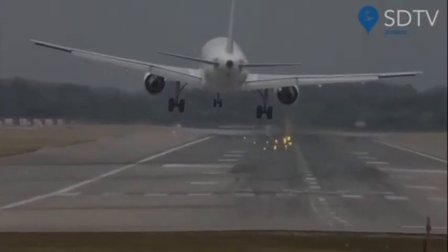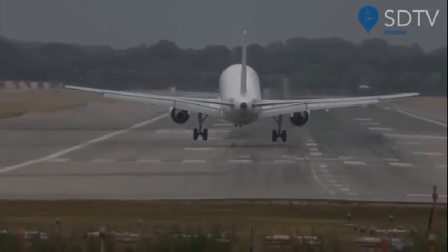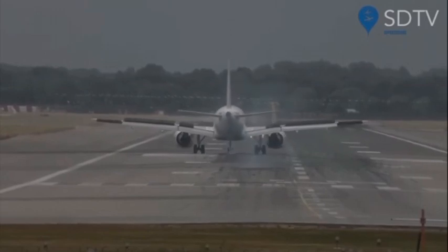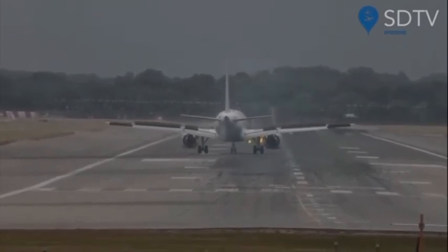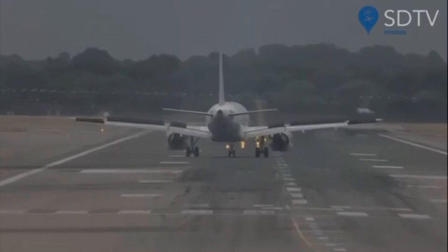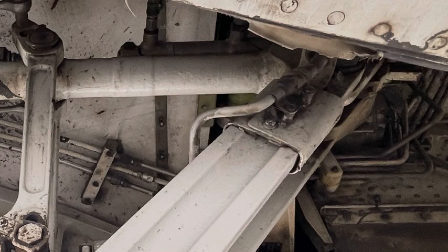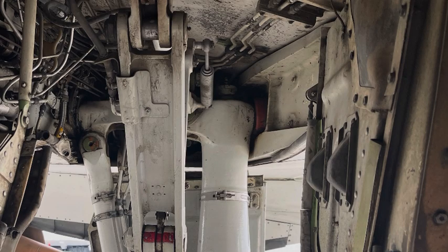And mostly during landing, because not all landings are successful textbook landings, there is often shock when the aircraft touches the runway. So the landing gear should be able to absorb this shock or force without transferring it to the other linkages and mechanisms where the landing gear is attached, in the fuselage or maybe in the wing.